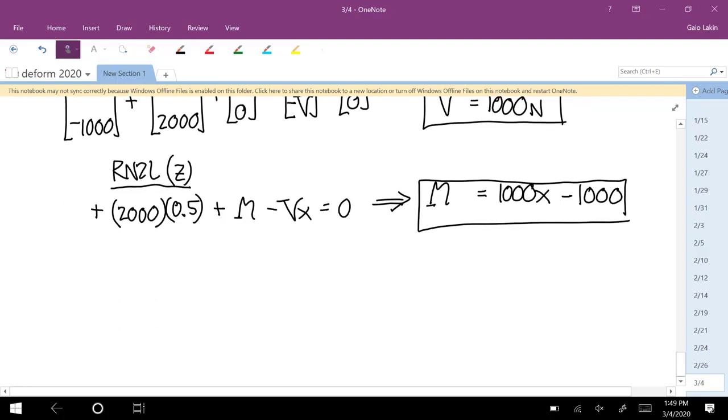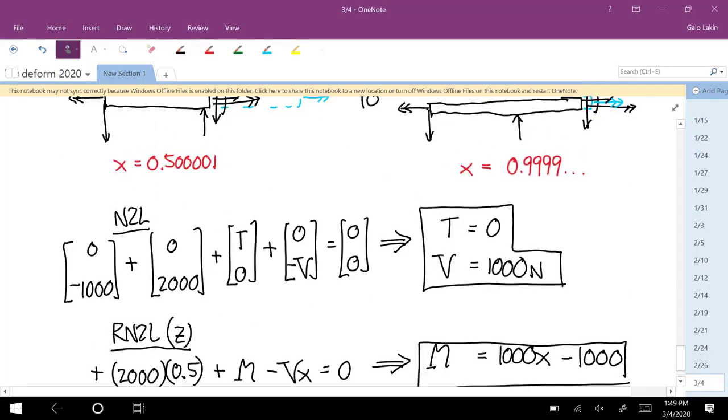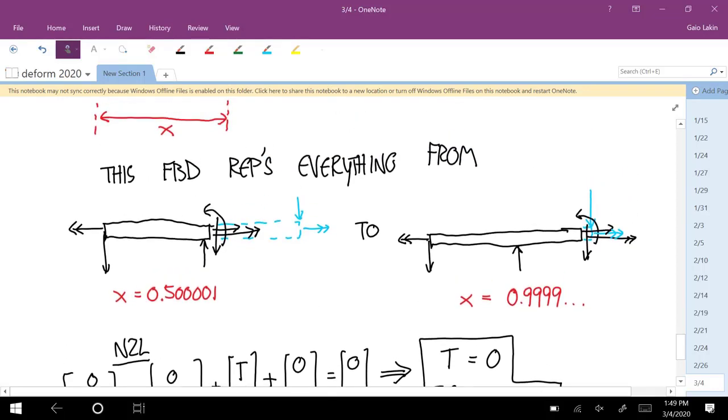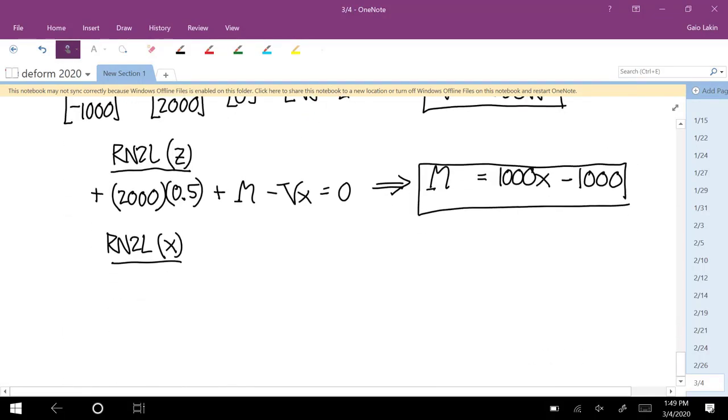And then the last one is for the x moment. So just add up the torques. That comes out the same as it did before. There was no additional torque happening at that roller. So we just have negative 500 plus fancy t is equal to 0. So fancy t is equal to 500 Newton meters.